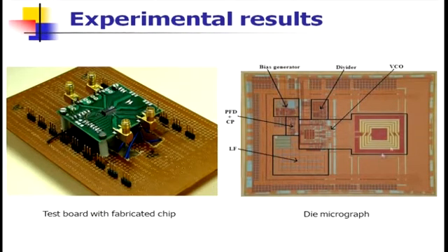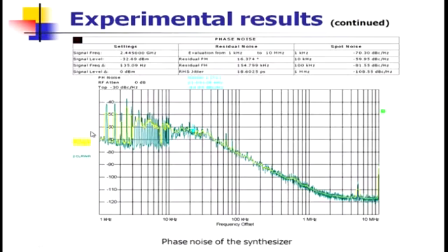So, this is a 180 nanometer design. Look at here, this is the inductor, and this is the VCO, divider, bias generators and so on, and this is a complete chip on top of the PCB. So, you will make that PCB inside. This is a relatively new one, which I showed earlier was lower, and then we go for the measurement of the phase noise.